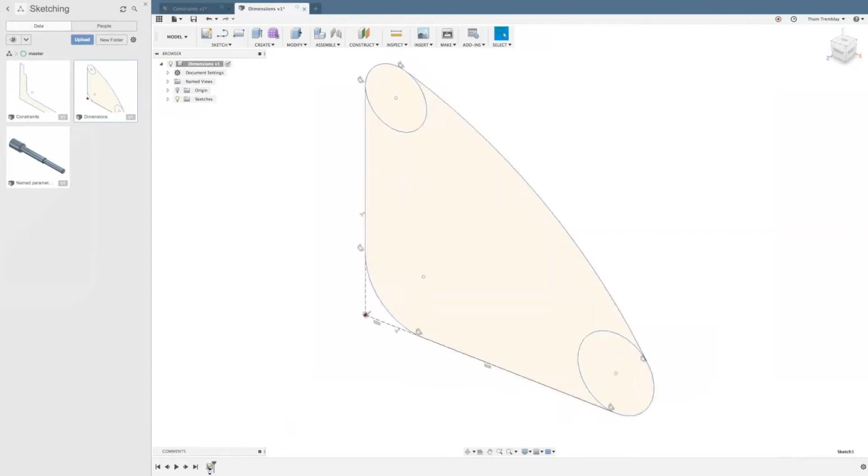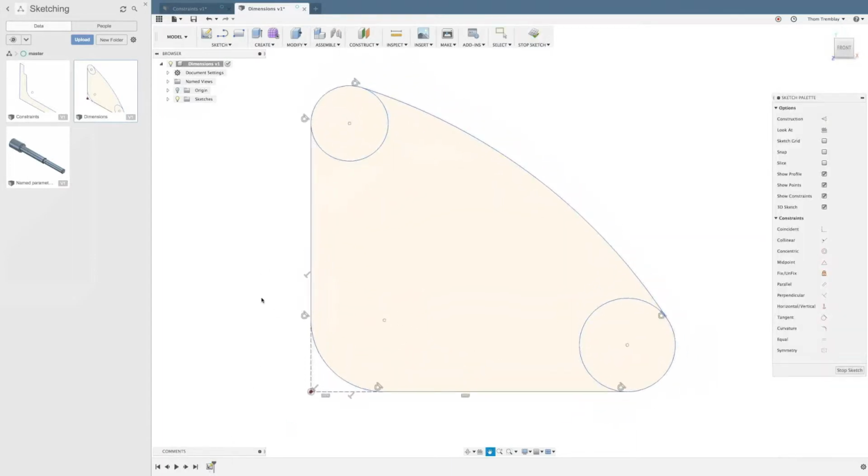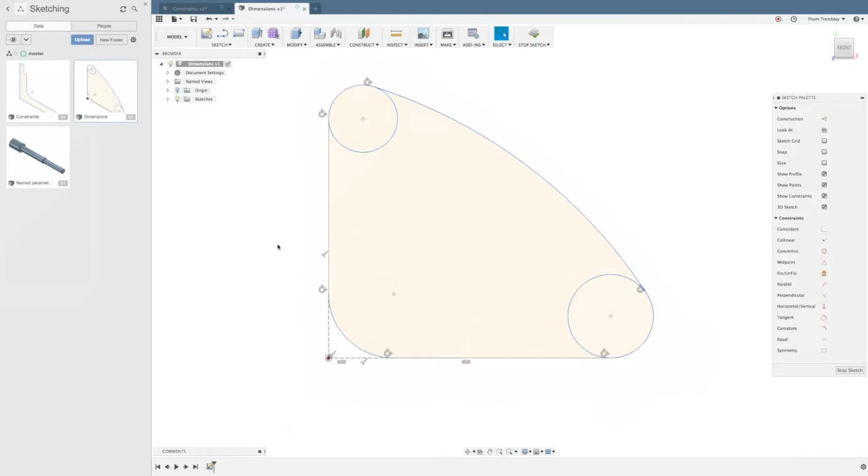Again, I'll activate the sketch to modify it. And let's just take a look at a few of the dimension options. First, let's just talk about dimensioning in general. So we'll start the dimension tool. I'll use the marking menu to go down to the sketch tools and then move to the left for the sketch dimension tool. There's just one sketch dimension tool.